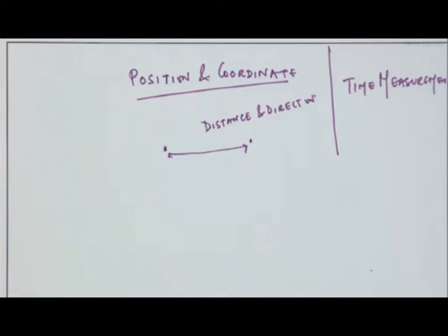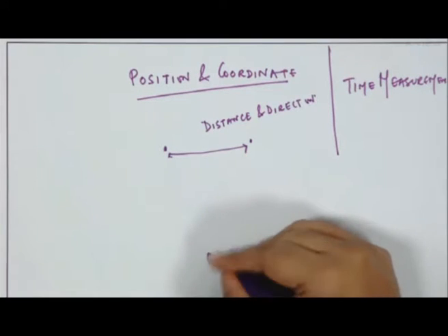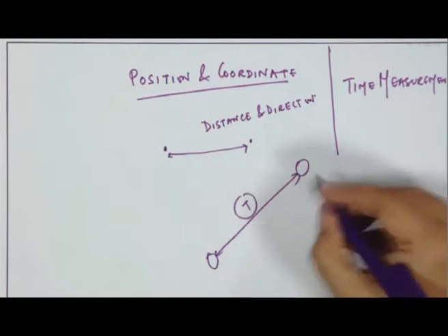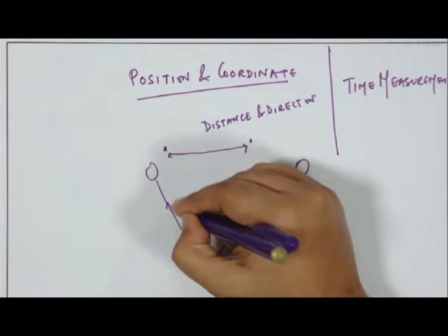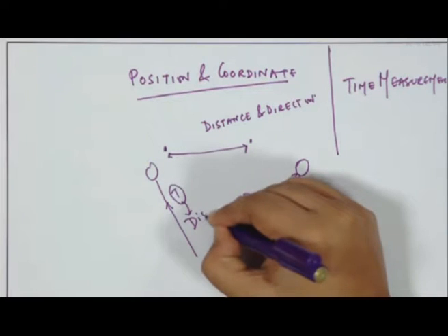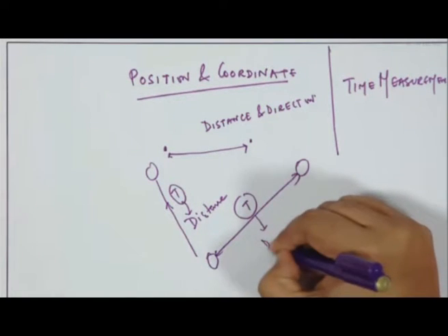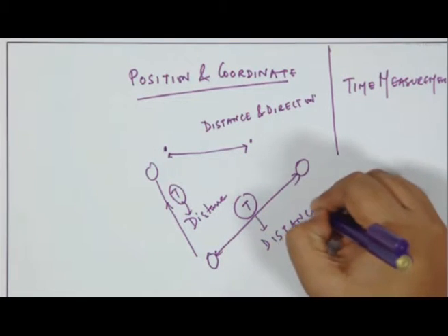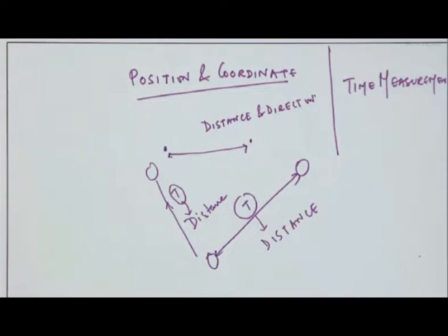So GPS works in three logical steps. The basis of GPS is triangulation from satellites. So we'll talk about triangulation. To triangulate, a GPS receiver measures distance using the travel time of radio signals. I am here, the satellite is here, and I see the time. There is another satellite, and I see the time. From that time I can get the distance. So I get distances from three or four satellites, and accordingly I can understand where I am.